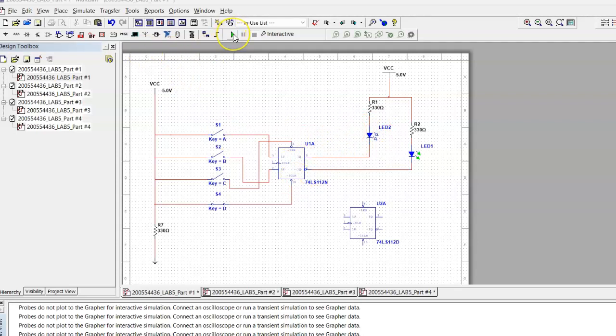So if I run the circuit, you can see that. I didn't close the other switch. I only closed the one connected to the clear. So you can see it's now in a high state, and the output Q is always 0. And if I open the switch and close this one, you can see the high state inside, and the Q output is always 1.